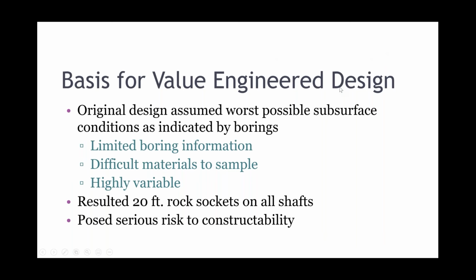All right, the basis of the value engineering design. So here after the contract's awarded, Malcolm Drilling is getting ready to go out there and put in drilled shafts. We got on board to help develop a value engineering proposal. As I noted earlier, the original design assumed the worst possible conditions based on the borings. And there was limited boring information. I know that cross-section I presented had five borings, but they weren't all where they needed to be. Also identified how difficult the material is to sample, and we certainly recognize the difficulty when dealing with highly variable conditions.